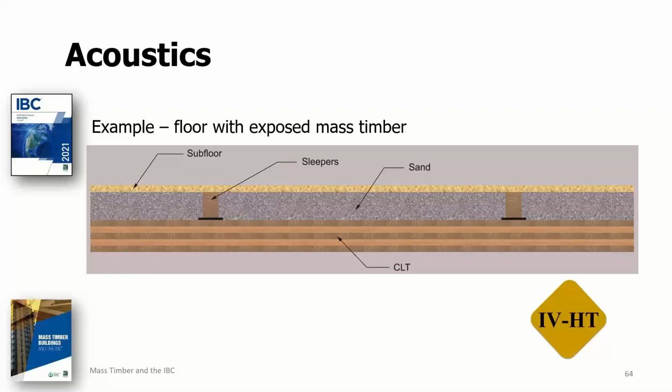In mass timber floor ceiling systems, the most common decoupling products are underlayments and mats placed between the mass timber panel and the concrete or gypsum-based topping. The type and thickness of material varies by product line and manufacturer, but the purpose is the same for these. It's to break the direct connection between the structure and the ceiling finish.